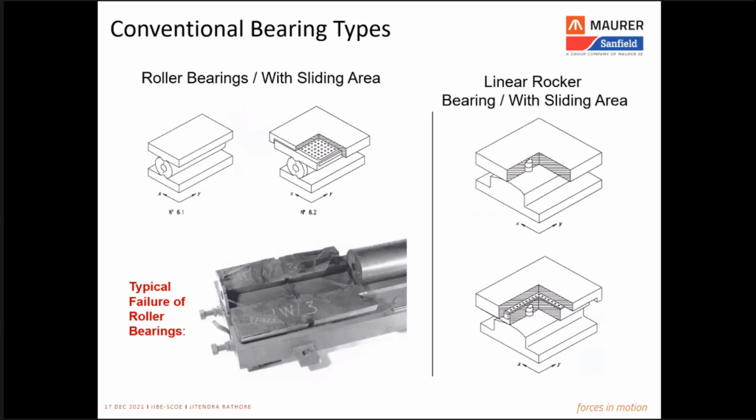If we break these up, 3 are associated with movements in 3 directions, longitudinal, transverse and vertical, and the other 3 are associated with rotations about these 3 axes. Depending on the type of application and the design of the structure, a bearing system may require anything from 2 up to 5 degrees of freedom.